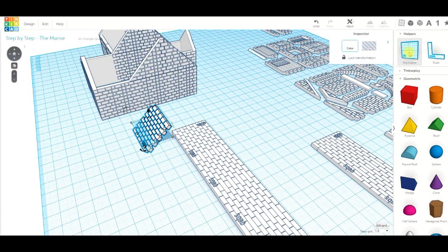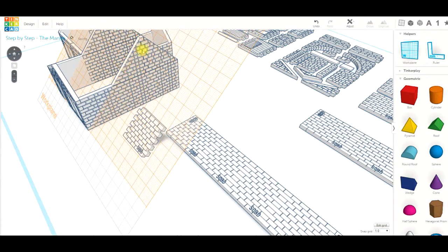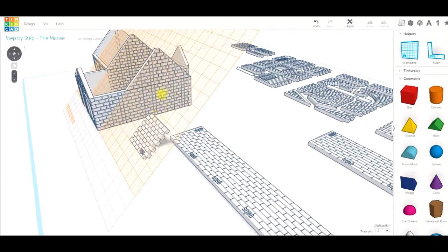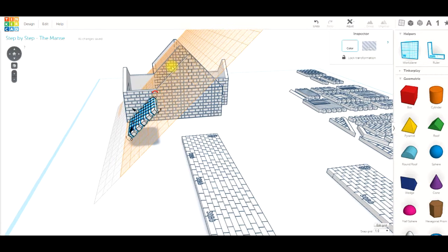So again, the work plane tool, and realistically speaking, you're going onto that face there, and if you notice, it's cut the grid right through the roof, so we know exactly where we're going. If I now use the arrow key, it'll bring it up to that grid plane. So when I get to 0, I know I'm exactly on line with that edge of that roof. Now I can either drag or use the arrow keys. I'm going to use the arrow keys, and because I'm looking at it from the side, I'm going to use the right arrow key because I'm sliding it right up the plane.